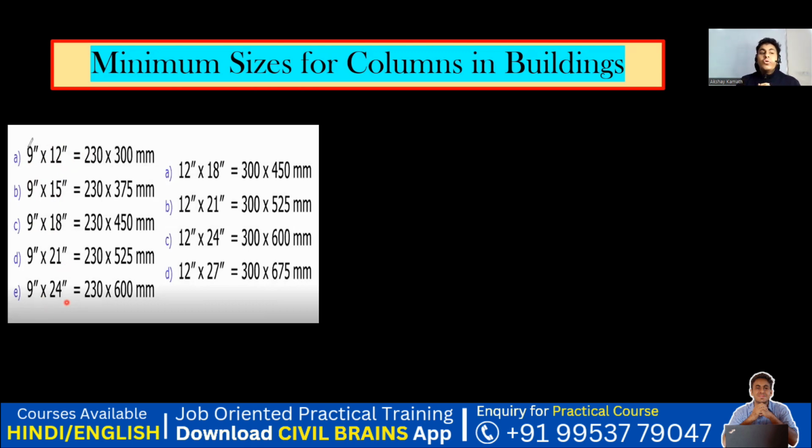Now, if you don't want to go with 9 inches, you can go with 12 inches also. So 12 inches comes out to be how much? 300 mm. Especially in the case of a commercial building, we go with 300 mm as the breadth of the column. So again, you can start with 12 inch by 18 inch for the commercial building. You can go with 12 inch by 21 inch, 12 inch by 24 inch, even 12 inch by 27 inches. These are the standard dimensions.